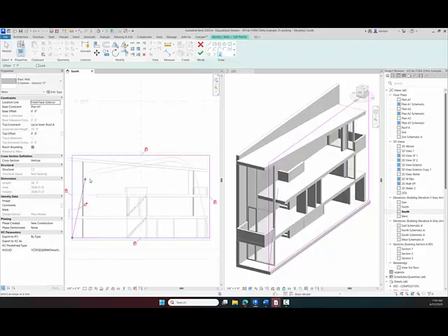I can come in and individually pick the curves from the linked drawing and then stop the pick line command, because I want to delete these three. But if I'm still in the pick line command and I pick one, it'll just keep making more. So you have to stop the pick line command by hitting either escape twice or selecting Modify.